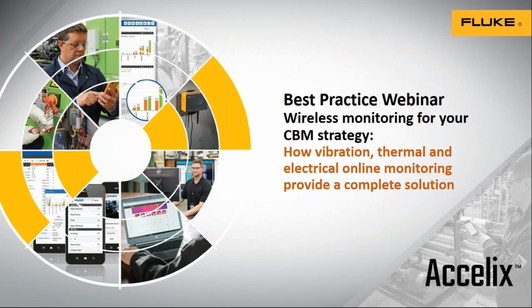Before you get started with your presentation, I wanted to ask you if you can tell us some of the major types of condition monitoring technologies that can be leveraged in today's facilities. Sure. There's really five, and so the first one is vibration, which is best for looking for mechanical faults in rotating machines. Then there's thermography, which is best for screening and supplementing three things: mechanical faults, electrical faults, and process problems. And then there's ultrasound, which is best for air and gas leaks, bearing lubrication and steam traps. And then number four, oil analysis, which is best for problems with the oil, as in lubrication and cleanliness and wear particles in the oil. And then finally, motor testing, which is best for motor electrical problems.